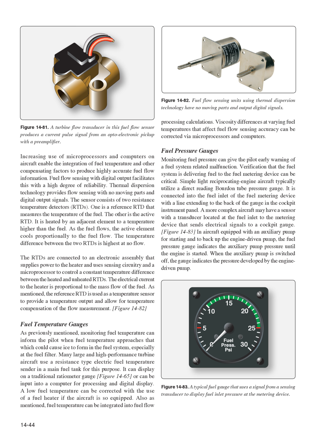A low fuel temperature can be corrected with the use of a fuel heater if the aircraft is so equipped. Also, as mentioned, fuel temperature can be integrated into fuel flow processing calculations. Viscosity differences at varying fuel temperatures that affect fuel flow sensing accuracy can be corrected via microprocessors and computers.